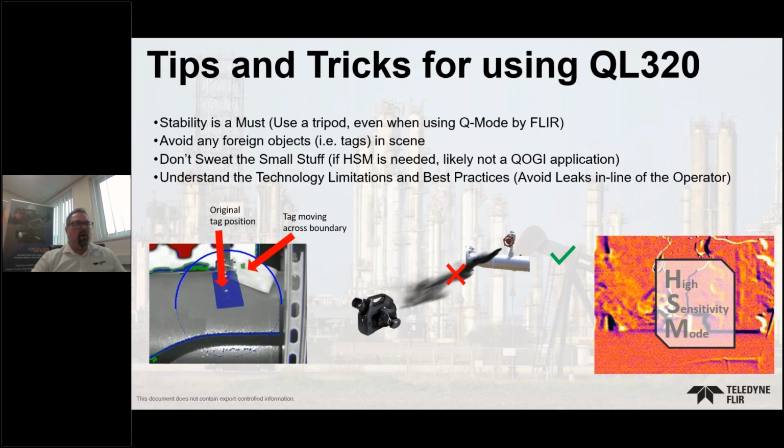Just to highlight: remove any tags, move them out of the way, and make sure that the gas plume is moving across the screen rather than coming towards you or going away. And if a leak can only be visualized in high sensitivity mode, that leak is going to be too small for the quantification.